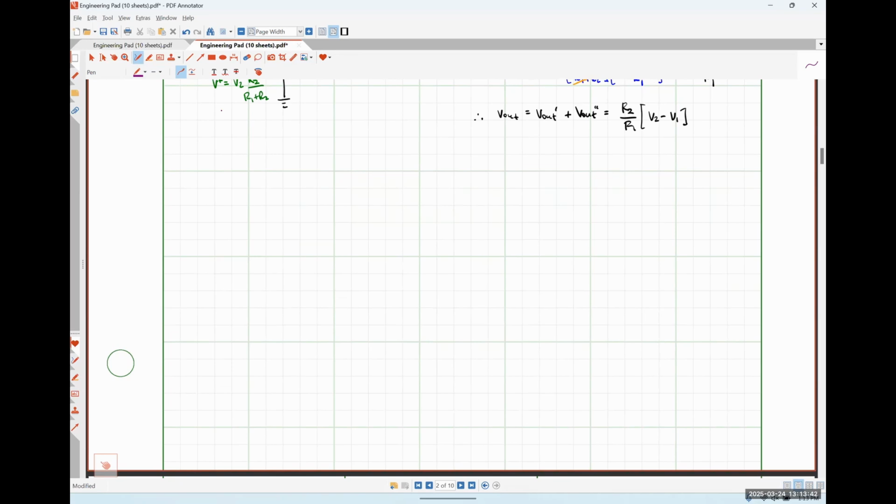The reason why typically in practice capacitors are used is because the tolerance of a capacitor is usually much smaller than the tolerance of an inductor. Meaning if you nominally purchase a 47 nanofarad capacitor, it's going to be pretty close to 47 nanofarads. Whereas if you were to get a 1 millihenry inductor, it's not going to be as close to 1 millihenry as the capacitor was to its nominal value.